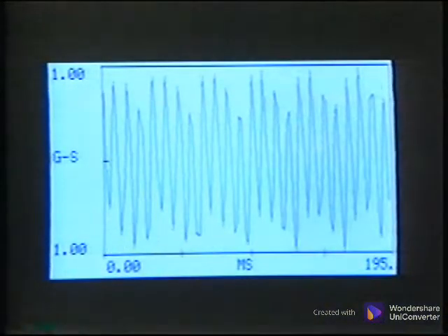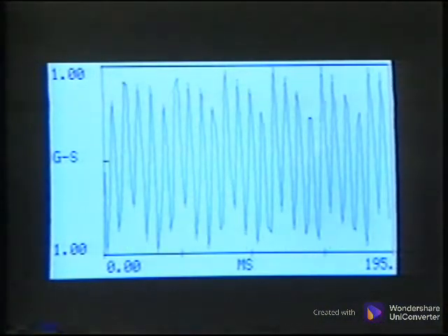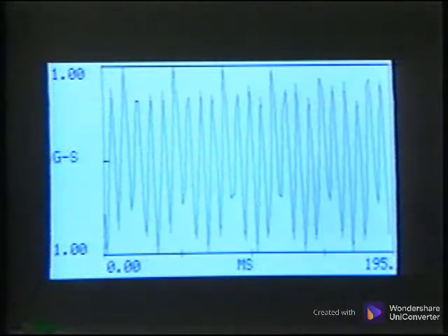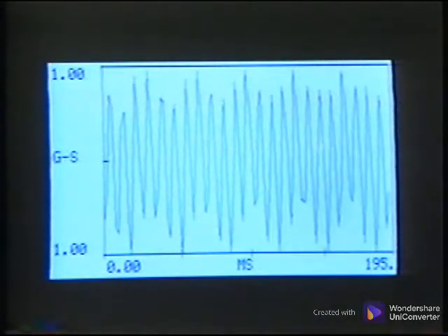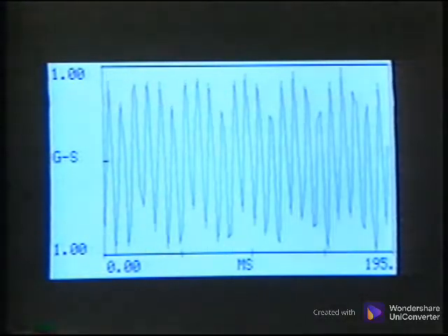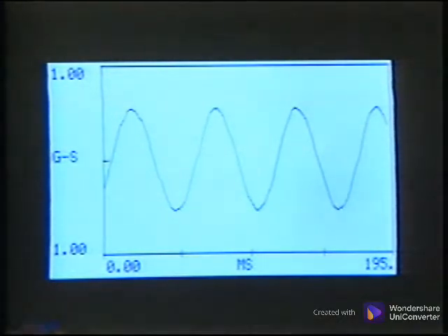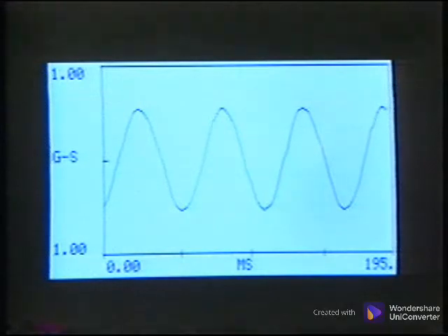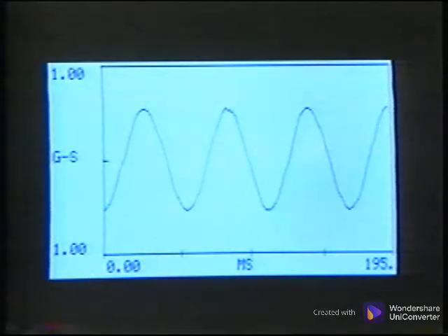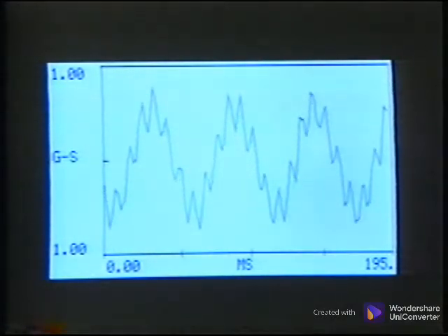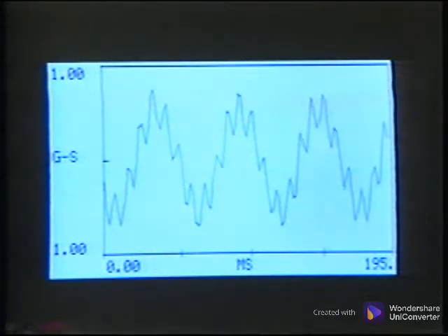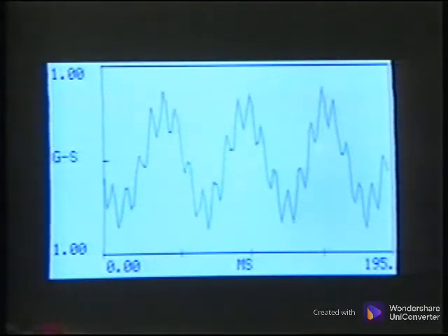The first signal is from the same rotor kit with a dominant unbalanced condition. Notice that this is not a smooth sine wave, but has other energy riding on it. The second signal is from a signal generator. The input frequency is 20 Hz and is a smooth sinusoidal waveform. The two signals combined show the amplitude variations as the signals add and subtract from each other, creating a more complex time waveform. This example showed the waveform data in acceleration.